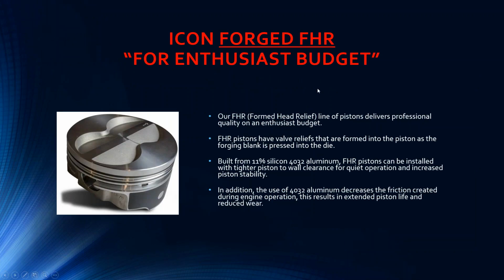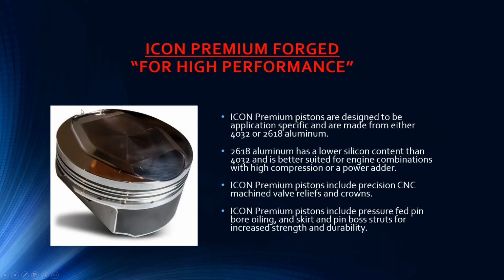Okay, here's a few offerings here. This is the FHR formed head relief, it's called. This is an Icon piston that's forged. It's the 4032 material. It is more for the economy budget for the race enthusiast. We have those available. We have the premium forge. It has the fully machined heads, and we have that in both the 4032 11% silicon or the 2618 less than 1% silicon. And we also have other features in it.